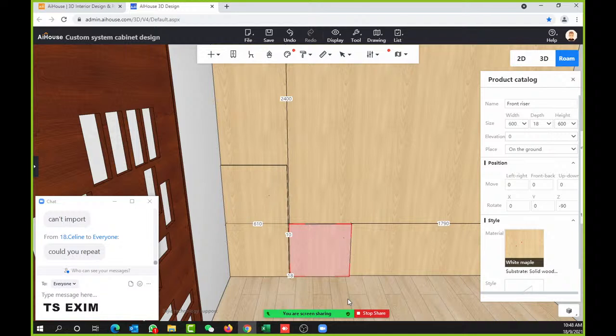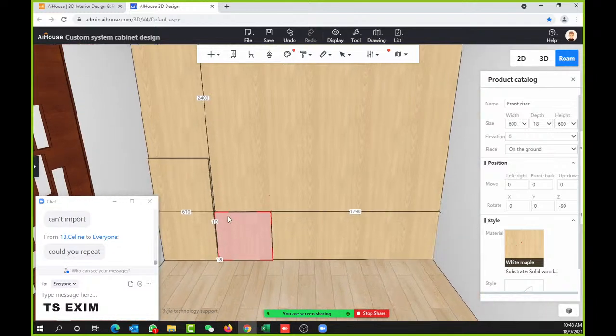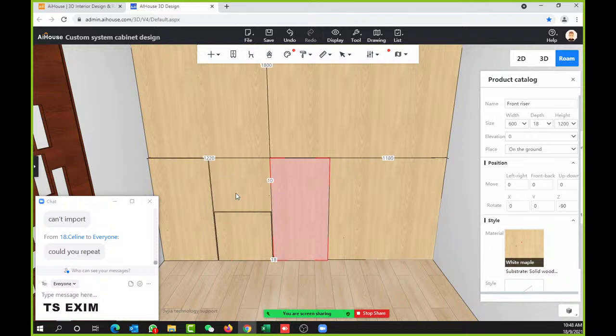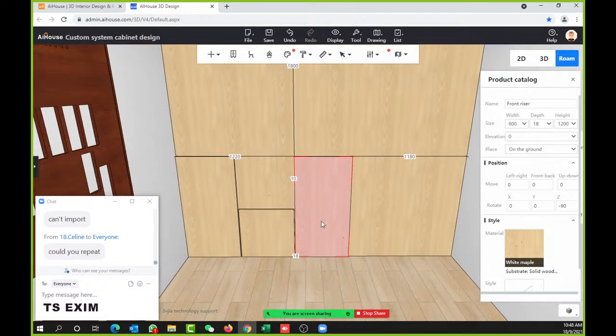Okay guys, time's up. So another one we just copy, very simple. You can click on here, right? We press Ctrl V. Then in here the distance we can add 10 mm for the gap, add 600 for just now the banner, then we add another 10 mm for the new gap. So you must be very fluent with your numbers. Okay, then you will automatically see also have a 10 mm gap here.